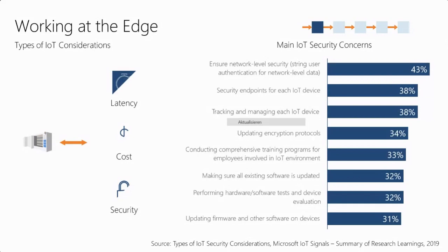These are the main IoT security concerns. The areas which I have highlighted at the right hand side are all active areas in which universities and researchers are working. When you enter into this arena and want to explore these, if you focus on the verticals mentioned at the right side, you will be working along these areas. First is updating firmware and other software on devices. Embedded firmware updating is a very, very hot topic. People use OTA, over the air updates, and they want to find ways to update the software in a more easy and transparent way.